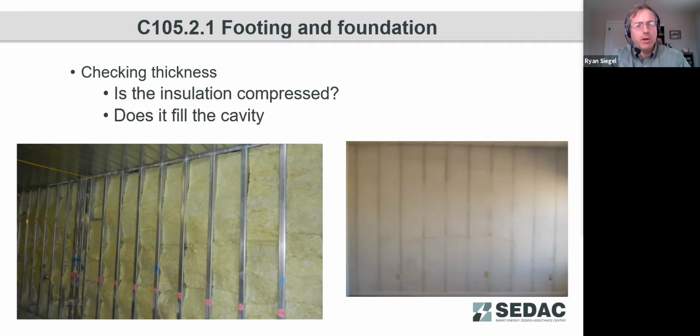Something else that we're noting here is, because this is a metal framed wall, one common issue that we run into following occupancy is what we show here on the right, which is ghosting that appears on the walls. So this is where that stud is not thermally broken and allows that heat transfer, in particular cold, to transfer through during the winter.